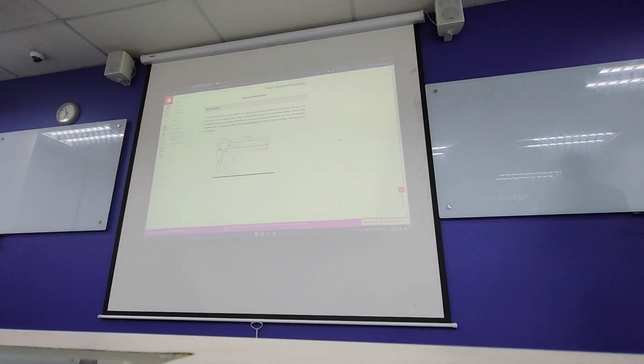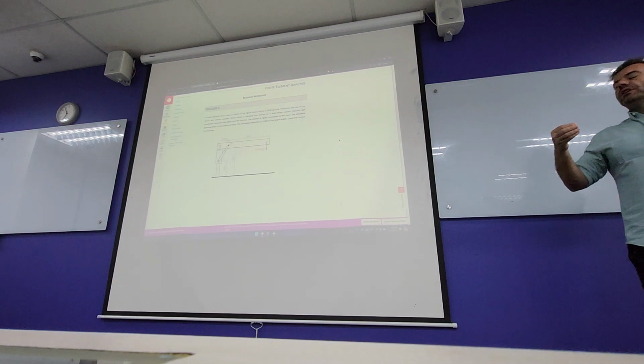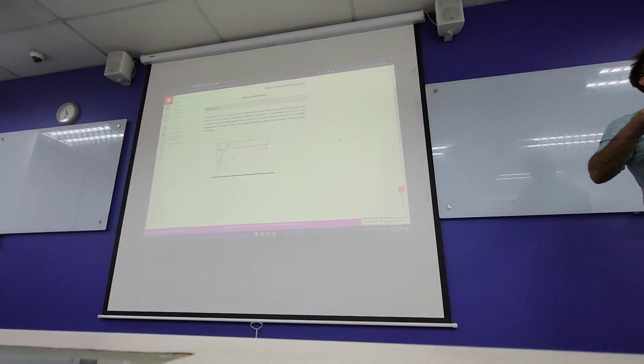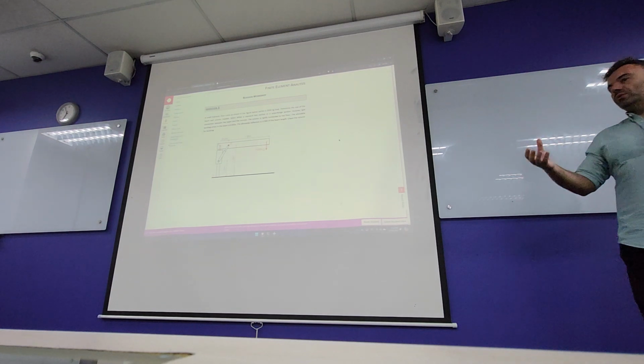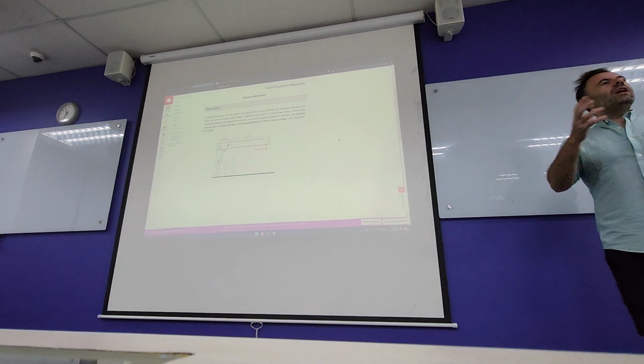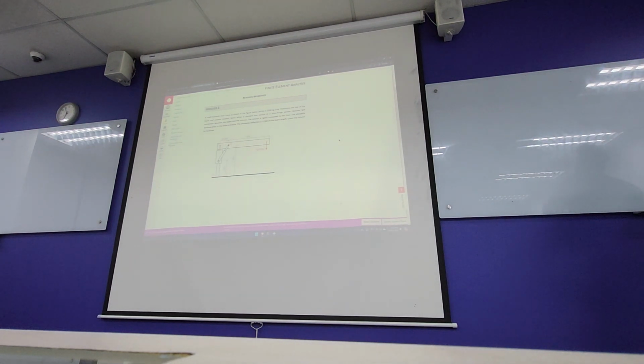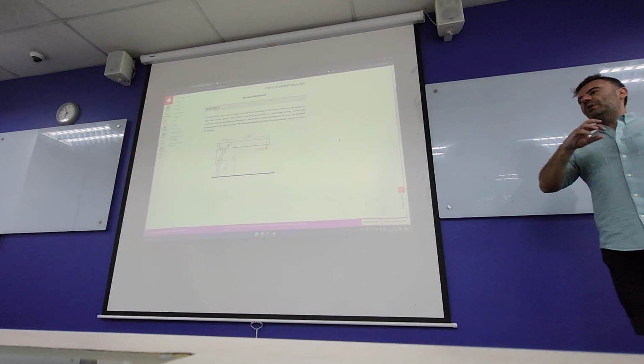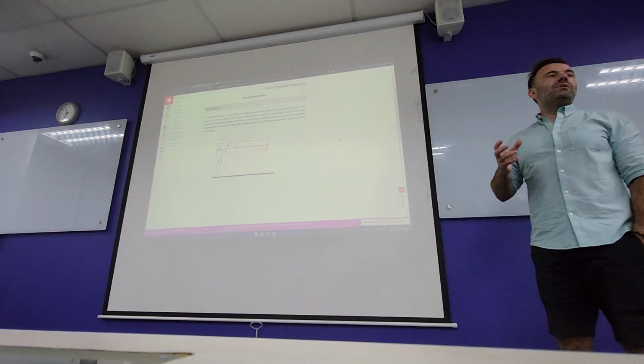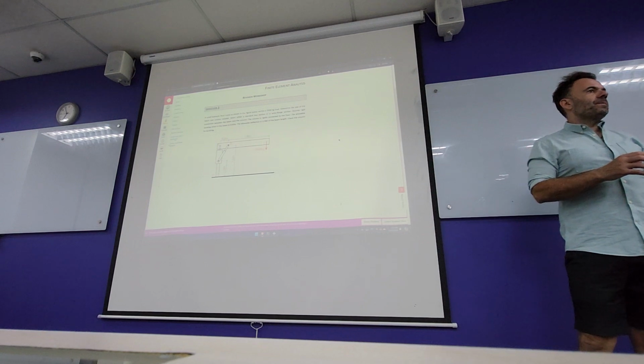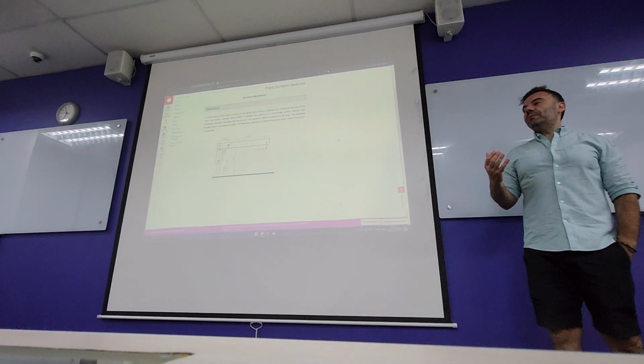Also to recognize where to put boundary conditions and what boundary conditions, as well as loads. And all other bits and pieces, like mesh quality, mesh type, mesh element type, and so on. So that's basically what you're going to be tested on.